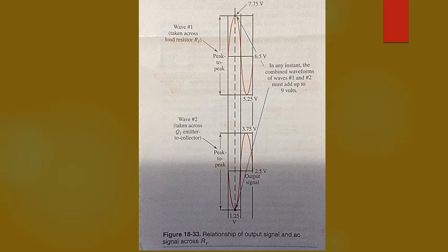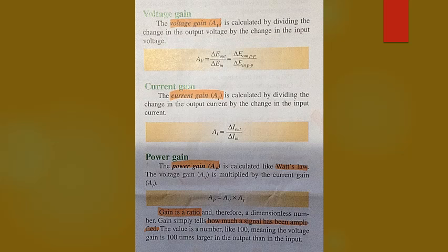A 0.05 volt signal in the input circuit, emitter to base in Q1, has controlled a 2.5 volt signal in the output, emitter to collector in Q1. This is amplification. Computing gain. There are a number of formulas that can be used to compute types of amplification in transistor amplifier circuits. When the formulas show a triangle or delta symbol, it means the change in a certain value or waveform.